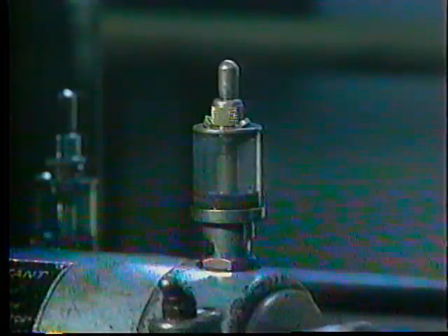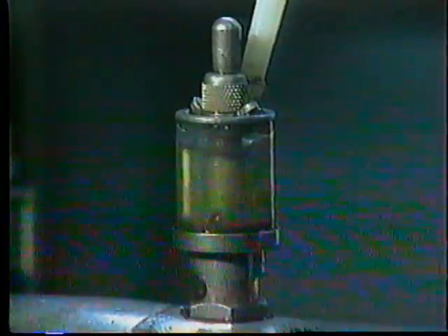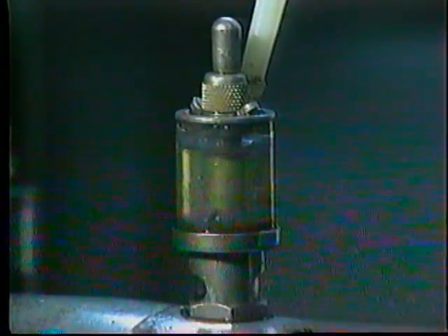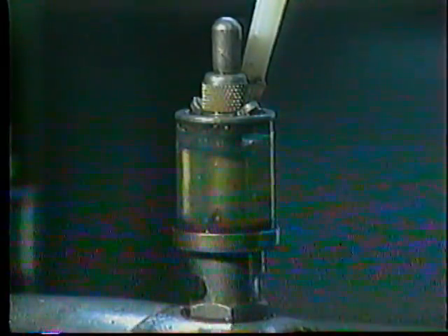Similarly, cup oilers are used to supply a controlled feed rate, but they use a needle valve to regulate the oil flow. Cup oilers, like other oil delivery systems with small reservoirs, need to have the oil level checked frequently. An oil mist system also uses the oil just once. Dry, compressed air generates a mist and carries the lubricant to the component. There are many other ways machinery is lubricated, from simple hand spreading of grease to spray-on dry lubricants to sophisticated automatic pumped grease systems that almost eliminate manual lubrication in some plants.